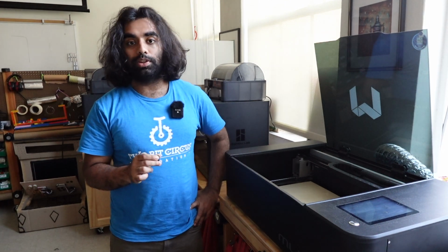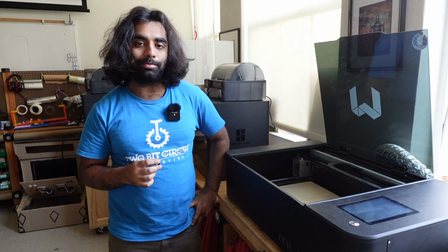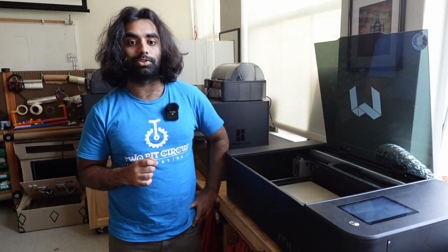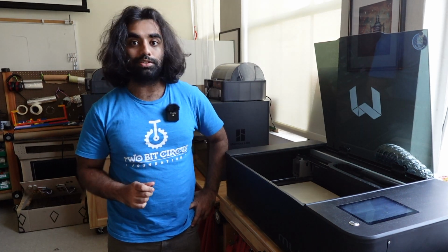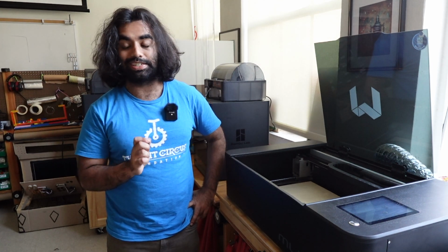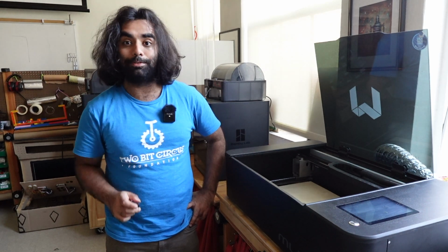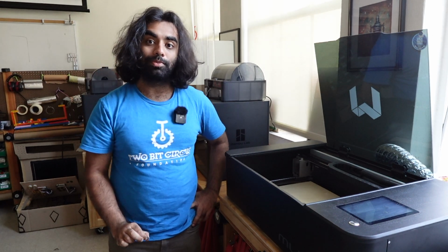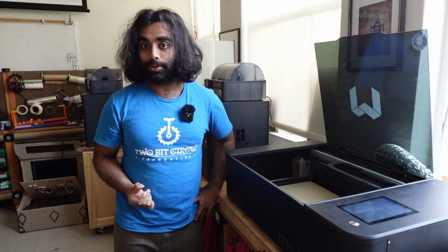You must focus your laser every single time you put a sheet of material into your laser cutter, even if it is 2 pieces from the same stock. It is an integral process, and we recommend doing it every time by utilizing this tool. In order to use it, you have to do the following procedure.